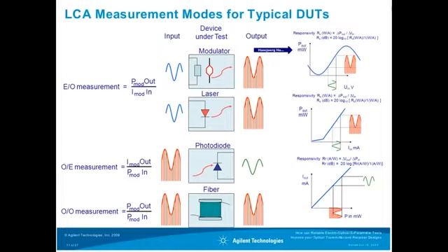an explanation of the responsivity of this device. For instance, for a modulator, if it's a lithium niobate modulator, you have this characteristic, this cosine square characteristic, and you usually operate it at a bias point, which is at the point of the maximum conversion. This is the quadrature point, and here you have the conversion of the electrical signal into the optical signal, and